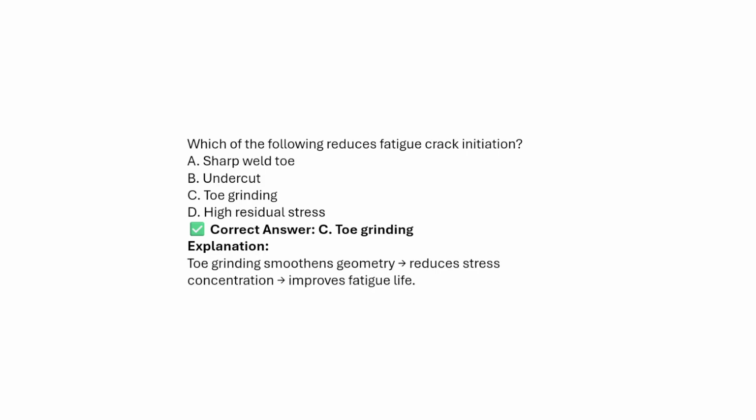Which of the following reduces the fatigue crack initiation? Sharp weld toe, undercut, toe grinding, high residual stresses. So the answer will be toe grinding. Toe grinding smoothens the geometry, reduces the stress concentration, and improves the fatigue life.